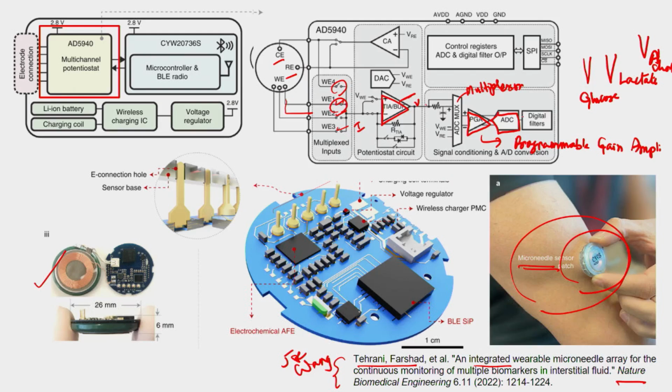Okay. So if I want, I can also implement digital filters. I can have a low pass filter. So let's say when we are moving fast, when we are running, the sensor signal causes some spikes. So we can remove these spikes using the digital filters.